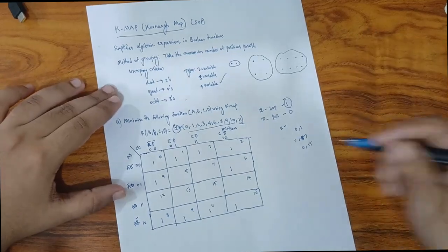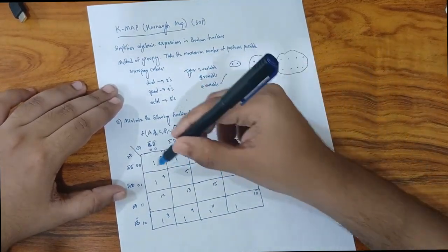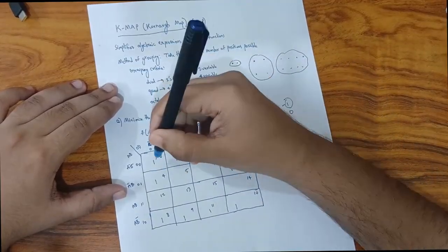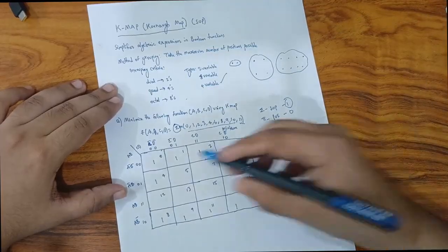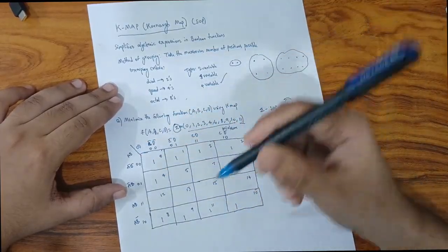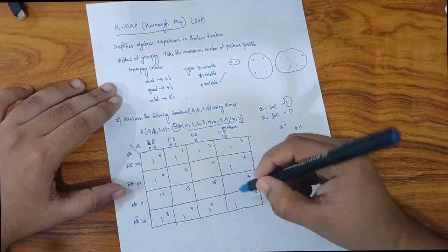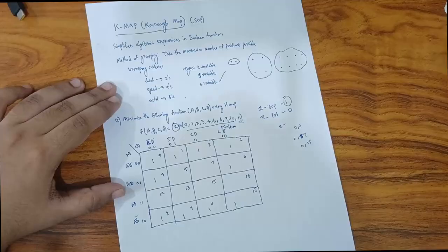We are seeing a lot of common elements here. They are adjacent to one another. You can see 1 1 1 1. They are all adjacent to each other, so we can put them under one group, I guess. But no, look down, there's another set of ones, 1 1 1 1. So you basically can't keep a quad.